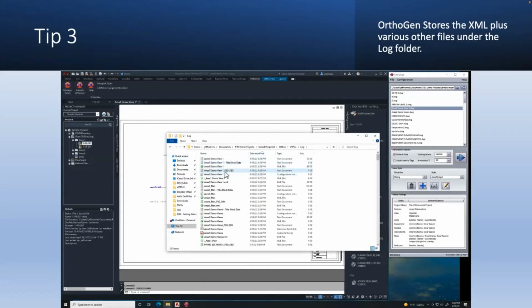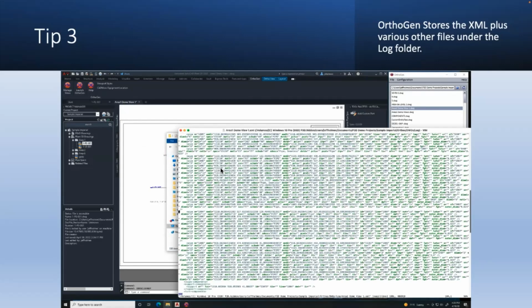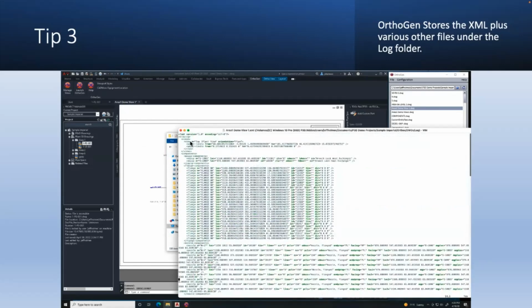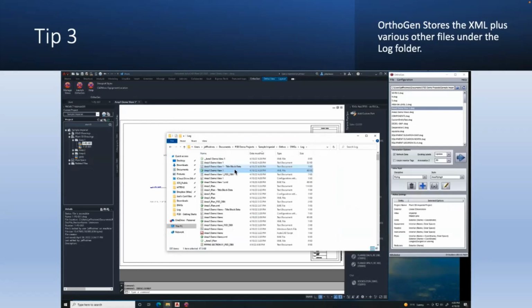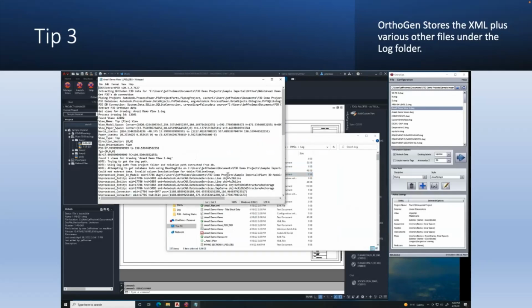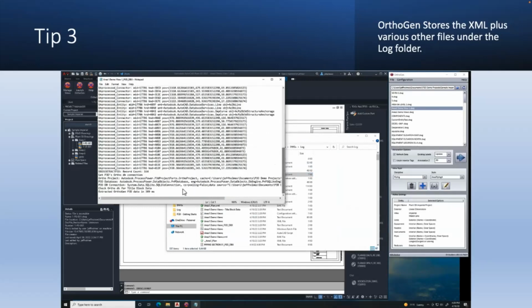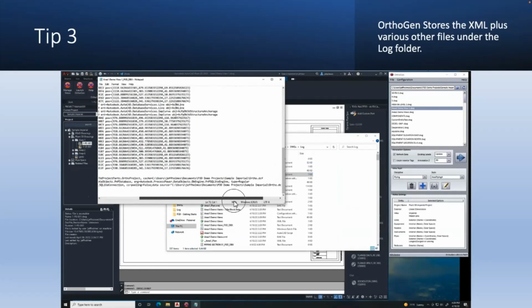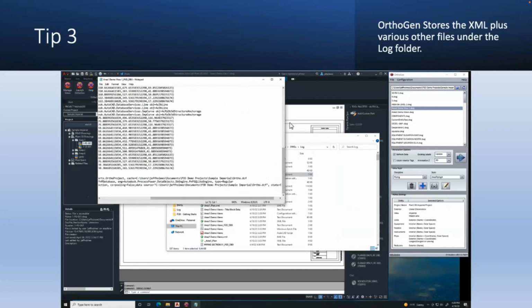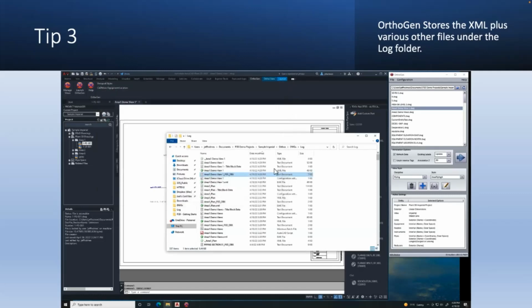So in this one, you can see a healthy XML file. This is what you want to see on your XML. You want to see data. You may not get into the details of what all that means, but at least there's stuff there. And then this P3D DBX log is one that you'll send to Marcus if you're not getting data. You see this one, the record count above was 164. Even in here, it shows you the database name. So those are two things that we'll get. There's also just a .log file that we may need as well.